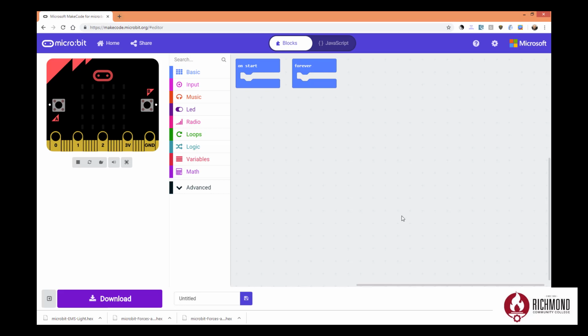So the yellow connection is the actual connection that reads the temperature from the sensor. The red alligator clip actually powers the sensor because the microbit can send out 3 volts, and then the black cable is the ground. So make sure that you wire your microbit properly to your water sensor. So let's start coding.